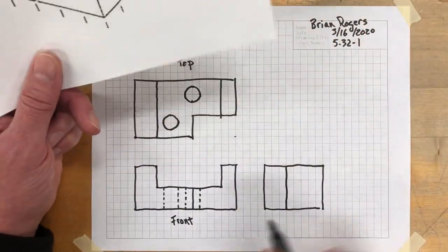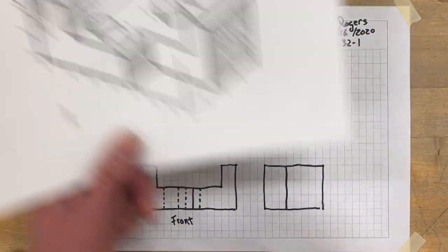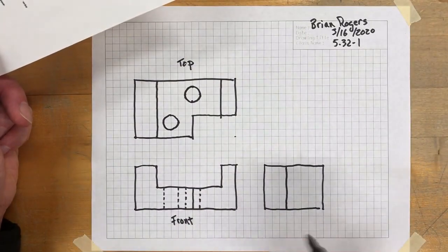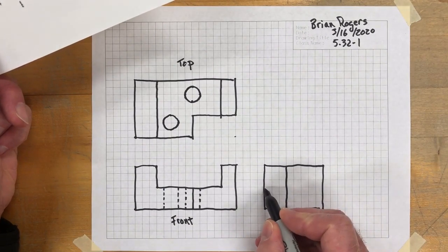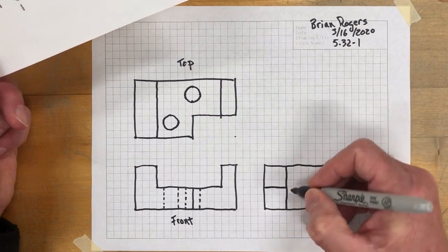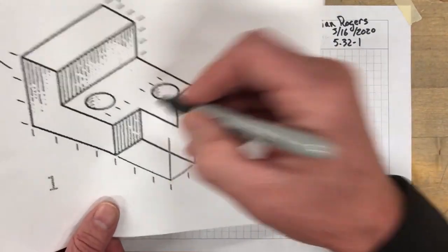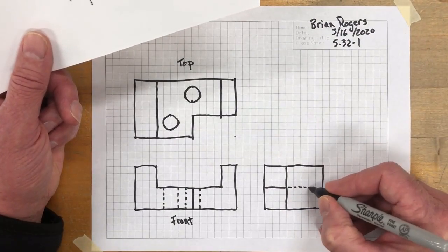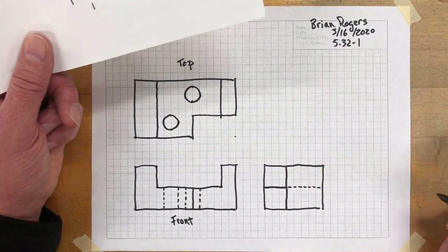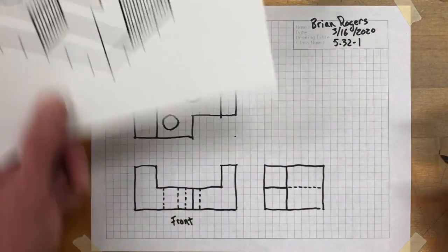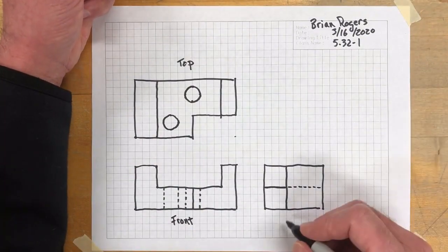Now I've got this bottom edge here. See this whole surface right here? It's right in line with this, so I just project it over from the front view. The interesting thing about this line is it starts out as a visible line because that's part of the cutout right here. Well, this surface continues on. It's going to go back here, starting at that vertical edge, and continue as a hidden edge because this part of it is blocking our view of it. So we've got the right side pretty well hammered out.